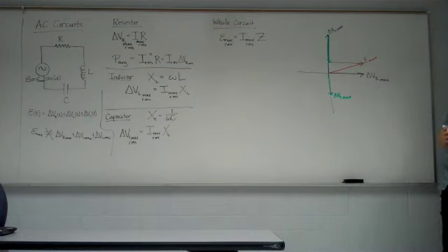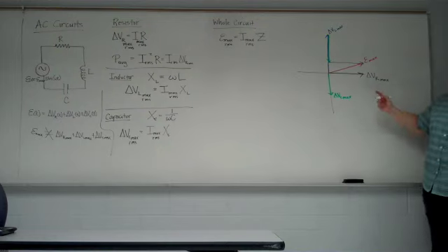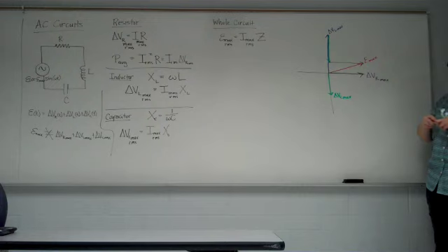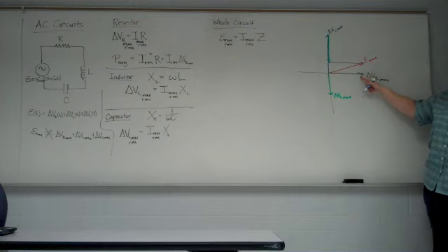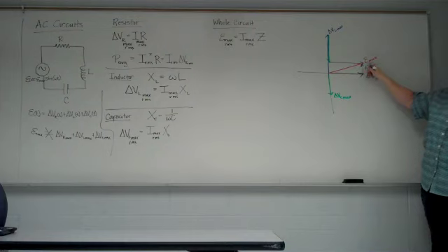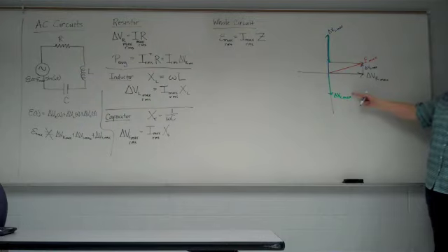So if we add them vectorially, the resultant vector represents the Emax, the source voltage maximum value. Now we have a really easy relationship between these. This is a right triangle. This side's the maximum voltage drop across the resistor. This side is the delta VL max. Now, if we write it just in terms of magnitudes, it would be minus delta VC max.